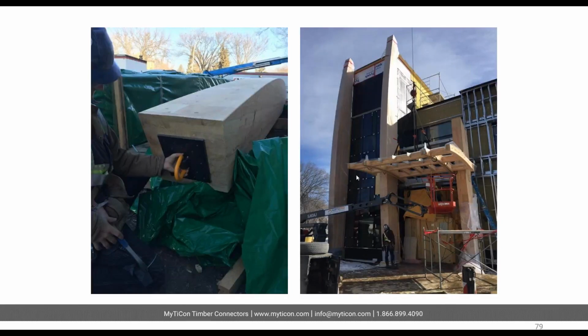And someone else has said, why should we use the sling angles at 60 degrees? For that, it's because the fasteners work better in withdrawal. If you look at pure 90 degrees, they're much stronger, but once it goes to 60, they're working in a combination of withdrawal and shear.